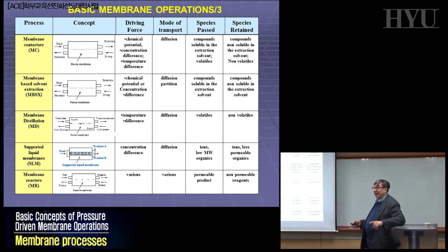All these processes are basically separations. Membranes can do much more than just separation. Membranes, as in nature, are the first example of an intensified system in which you can combine more functions. Membrane reactors are systems in which separation and chemical conversion take place in the same membrane unit. You can have a membrane which is catalytic. You can immobilize a catalyst in the membrane itself. So you can have a system in which you can continuously convert and separate if the membrane is selective.